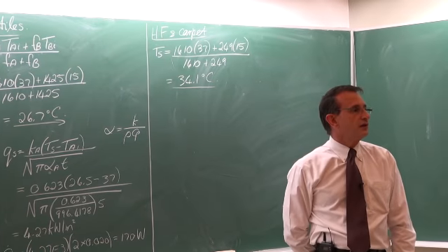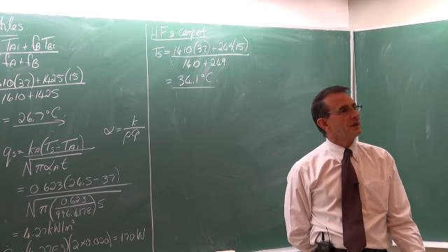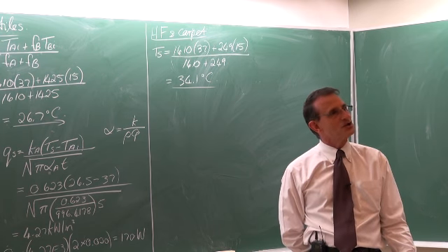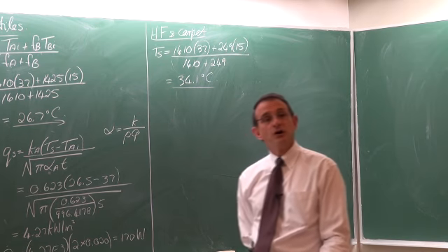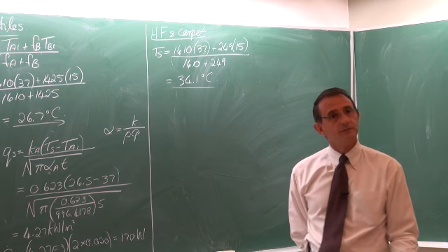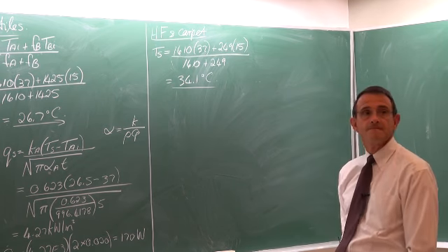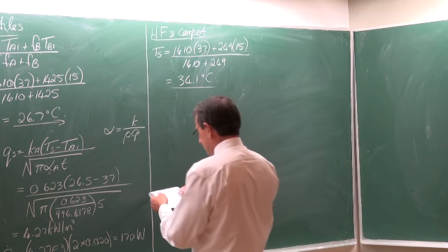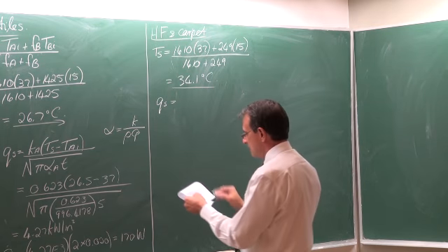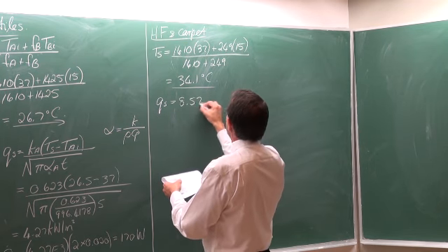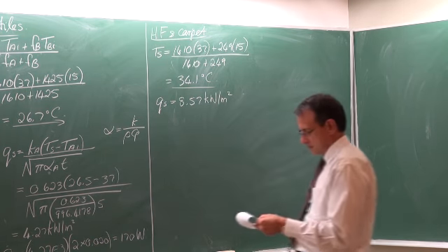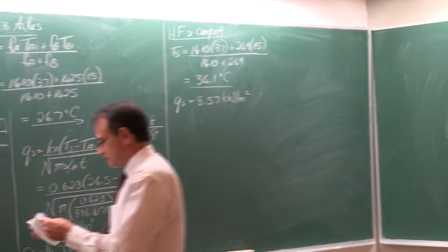So that is why it feels that when you get onto the carpet, that the carpet is warmer. But that's not the case. It is just the surface temperature between your feet and the carpet which is at a higher value, although the bodies are at the same value. If you go and calculate the heat flux, it is equal to 1.18 kilowatts per square meter. I'm not going to write it out. We've already done that.